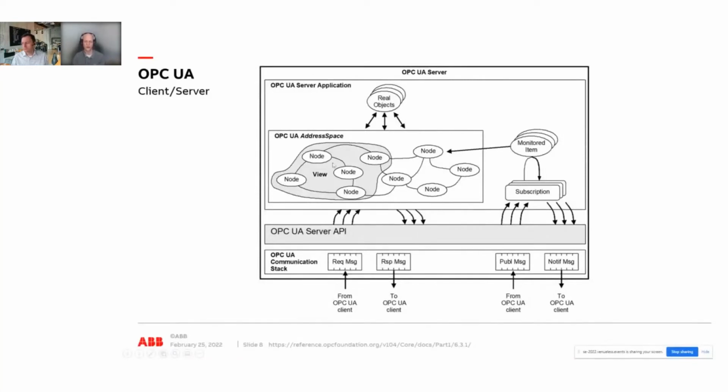And these nodes here represent actual sensor values in the real world. For example, the filling level in the tank could be expressed by such a node. Clients can then register for subscriptions to those values and get live updates constantly. You can also put control signals in here, for example, the opening level of a valve. So this allows you to interact with the entire plant.